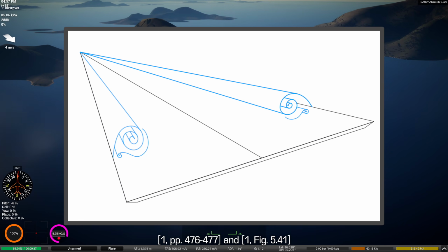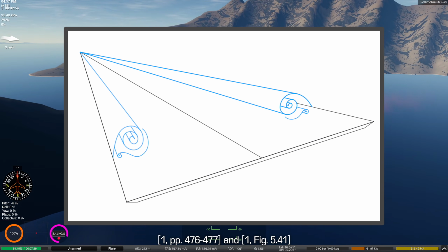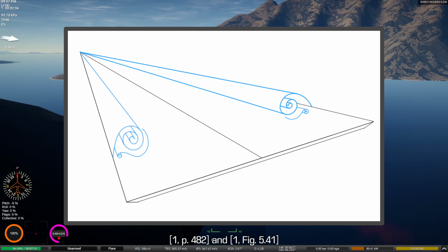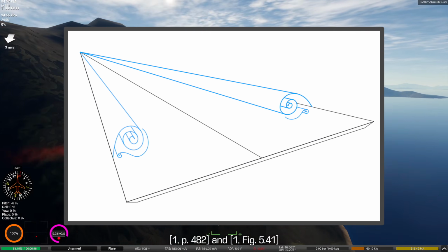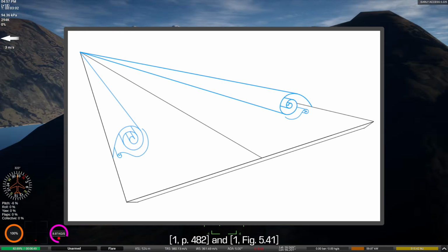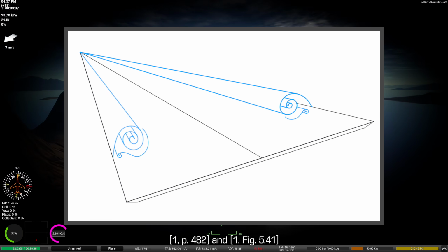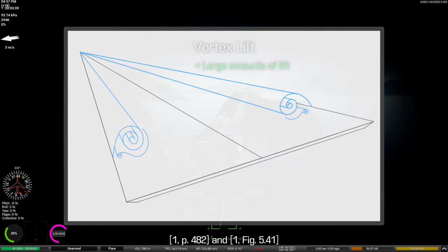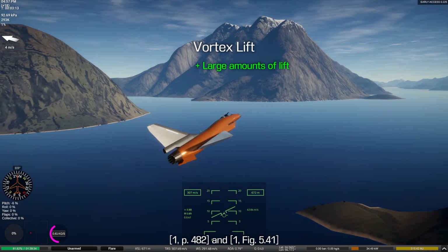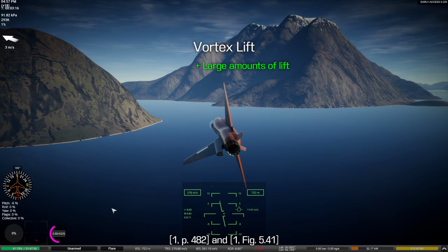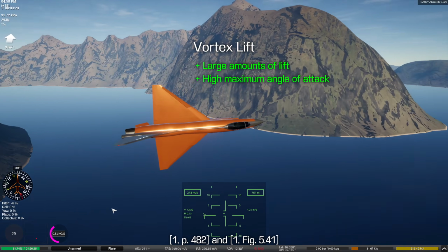These leading edge vortices are a result of flow separation at the leading edge due to the sharp corner. The static pressure in these vortices is low, which causes the pressure over the upper surface of the wing to be lower near the leading edges, while the middle section is also relatively low. This results in an extra lift contribution by the leading edge vortices known as vortex lift. The presence of these vortices allows for the air to remain attached to the wing at higher angles of attack than it would without them, allowing for delta wings to achieve very high angles of attack without stalling.